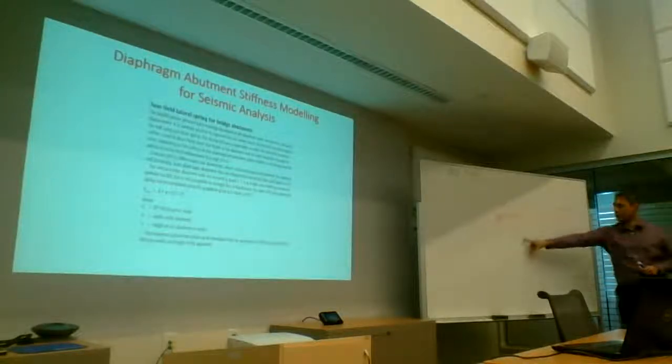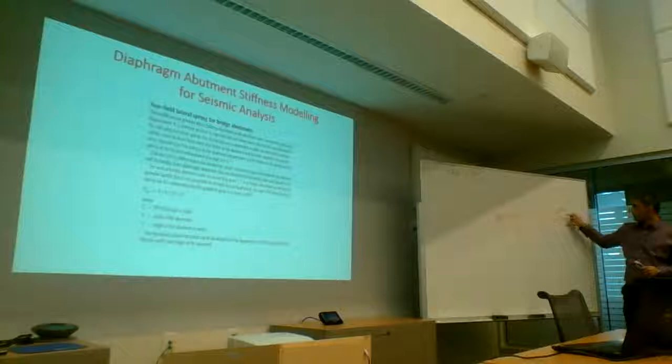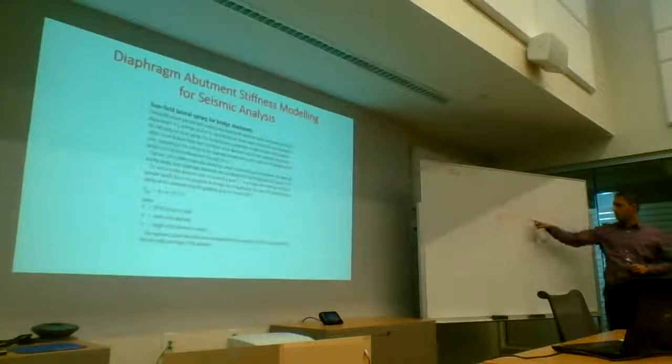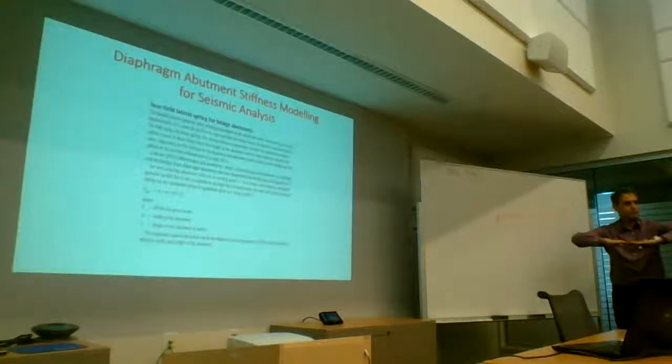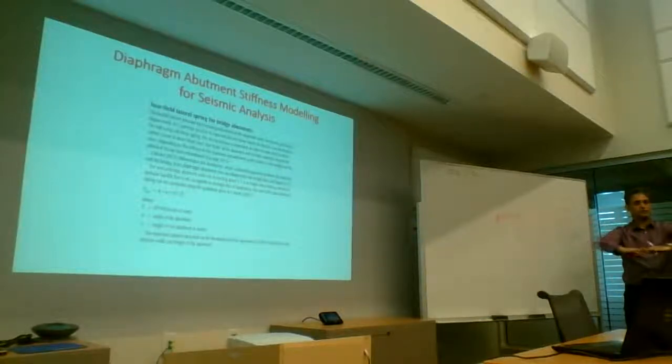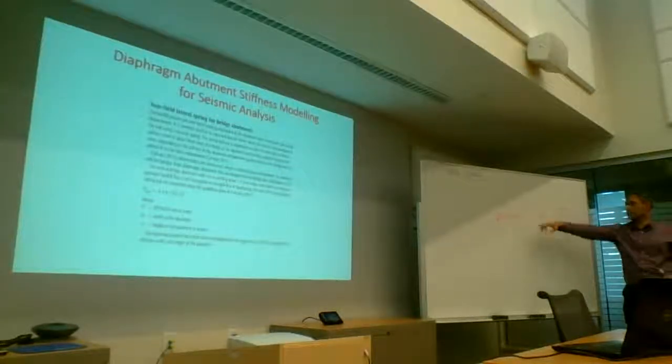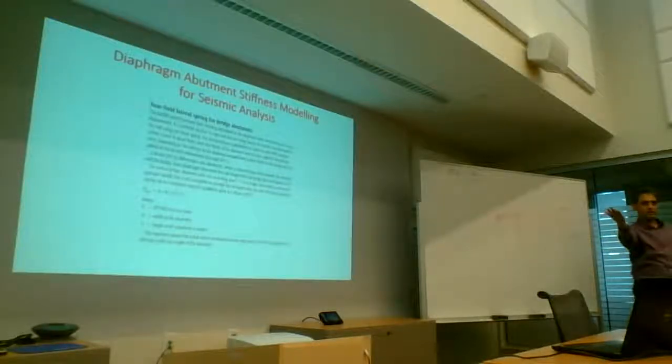Okay, so these are your piers. Even if my abutments are very, very stiff, but my deck is very slender, the deck is not going to act as a rigid diaphragm. It's going to bend itself. And when it bends, it's going to drag the columns with it. The columns have deformation, which then turns into moments and shear forces.